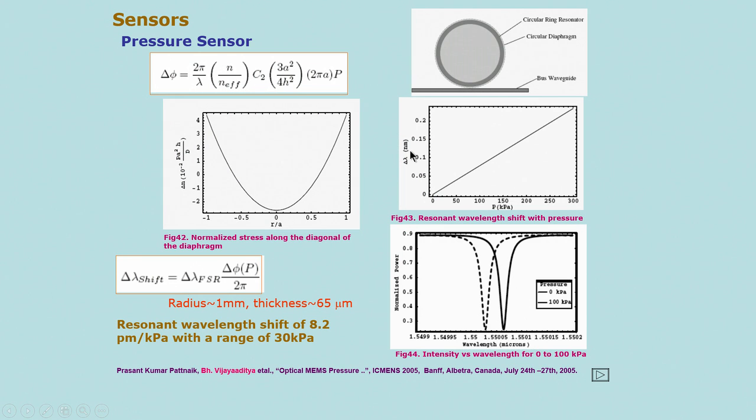So, this is an example of application of the ring resonator to a pressure sensor. We have seen the pressure sensor made on a Mach-Zehnder interferometer earlier, where you had etched out a diaphragm. You had earlier an interferometer like this, and on one of the arms of the interferometer below you etch out a diaphragm. In this case, from the mechanical analysis, the stress variation is maximum on this waveguide, and so maximum change in the delta n, and the optimum pressure output.